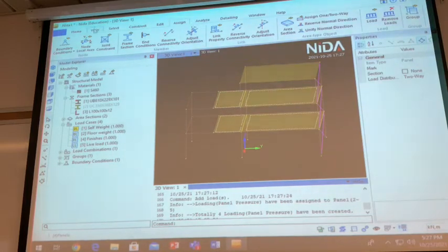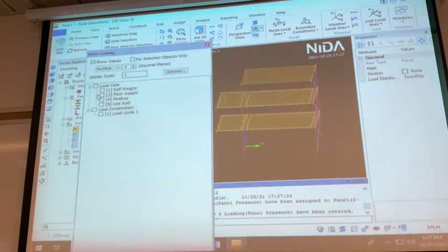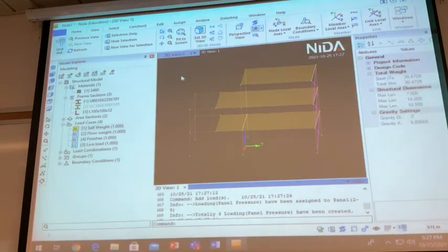I can go to the View pull down menu and then here. Floor load, 3 and 2, yes. And then finish 0.5, yes. And you can see the direction is downward, yes. Live load 5 and then 3, yes. When you keep all the boxes, they will sum up together, so I just prefer you check it one by one. Self weight, you can't see the self weight, but okay. All right, it's done. The loading is done.